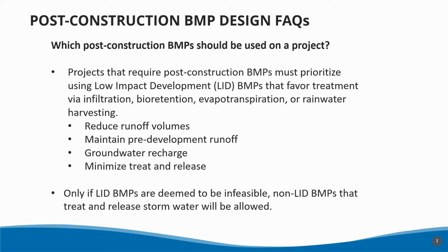So which post-construction BMPs should be used on a project? We definitely leave that up to the designer's discretion. But we do have a priority for LIDs to be installed first. That should definitely be the priority. The reason for this is, it's in the MS4 permit, and we definitely want to increase the number of LID BMPs being installed.